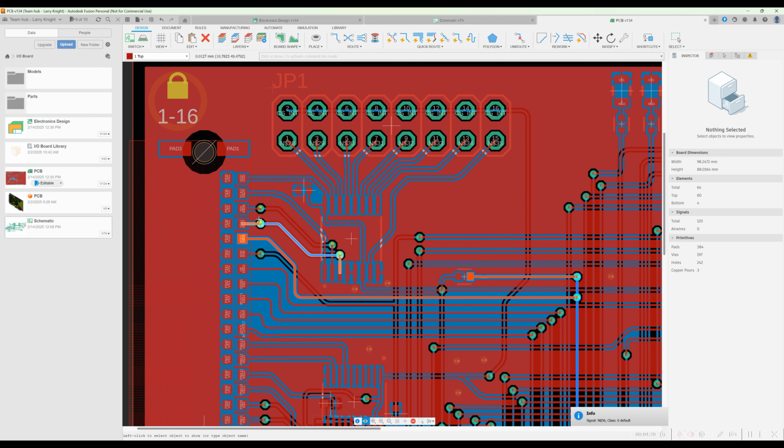So let's just stick the resistor on the board right here, solder it to this pin of the connector, and we'll just run a wire from the end of the resistor over to VDD. All right, let's do that.